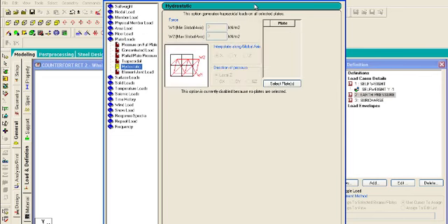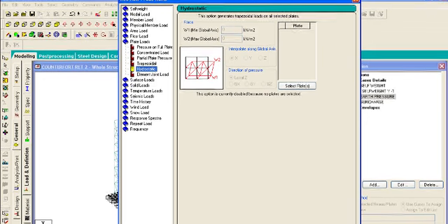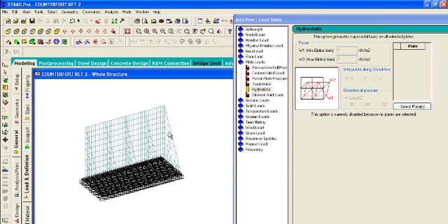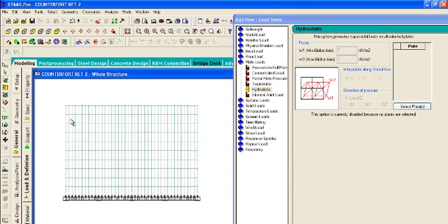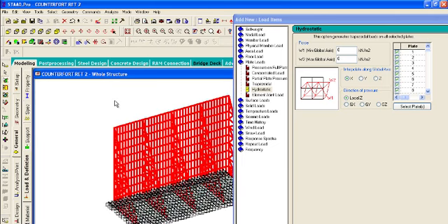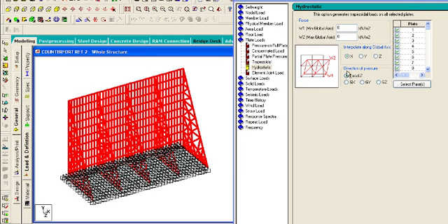So we have to treat it as a hydrostatic load. So we have to select the members. If we change the view, we've been able to select the members that will experience the earth pressure action. It's in the global y direction.